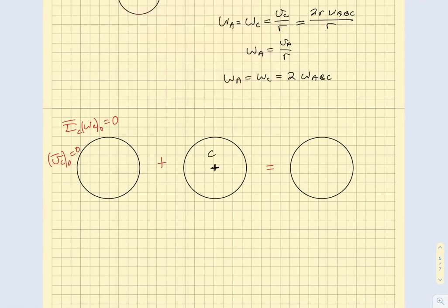Then we have the external impulses for the gear itself. Now remember, we have two things to consider. There's going to be some force that's going to drive this along the direction of VC, as we had mentioned before. So what we can do is isolate these and say this is the center of the gear here, location C. Because it's a pin connection at C, there's some two-component interaction at that location. We can break this into components.